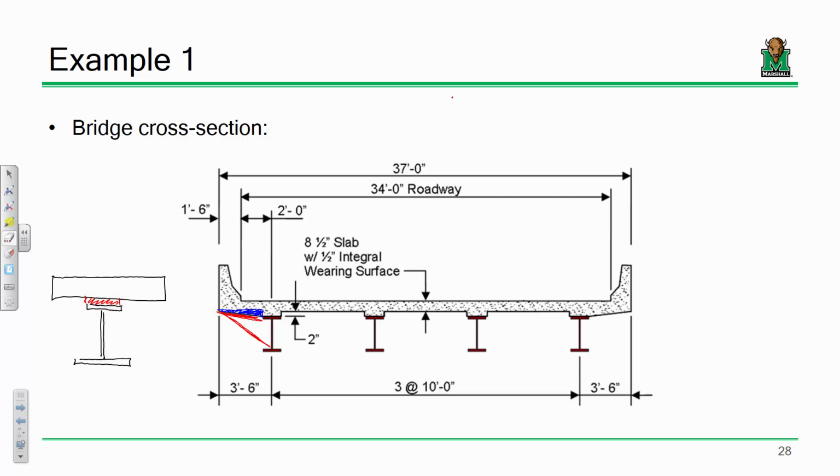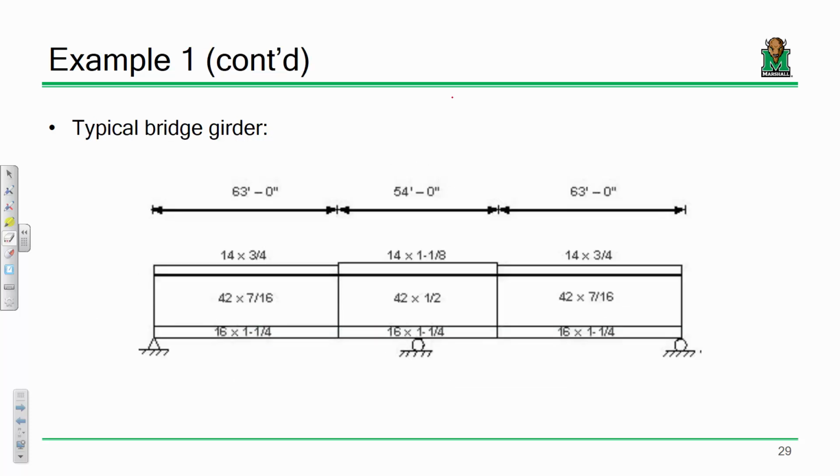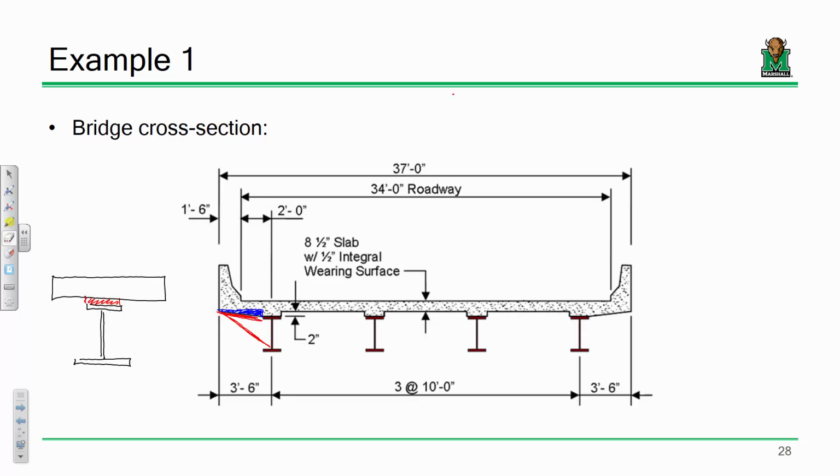Now, you all by now know the secret weapon of structural engineering. Do you have to account for the equipment load? Like the equipment that's used to pour the concrete, finish it, and all that? When you're assessing the constructability limit state, like the survival of the bridge during construction, absolutely, yes, you do. The screed rail, the finishing machine, the bid well, all that.